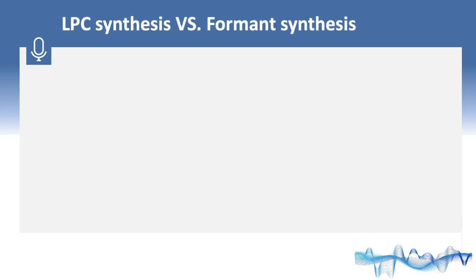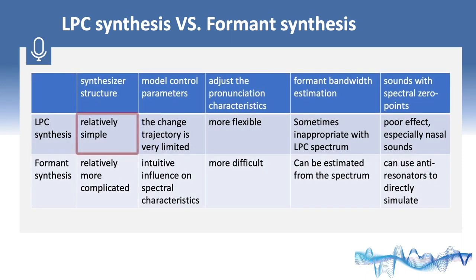Firstly, LPC speech synthesis has relatively simple and fully automatic analysis steps, and the structure of the synthesizer is relatively simple. When the lattice filter is used, the quantization characteristics and stability are better, and the hardware implementation is easy. While formant synthesizers require more parameter adjustment, the synthesizer structure is relatively more complicated.